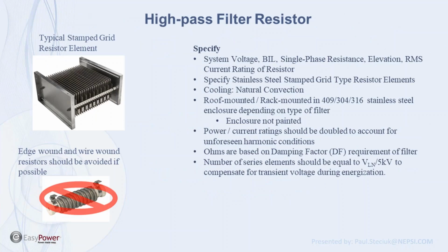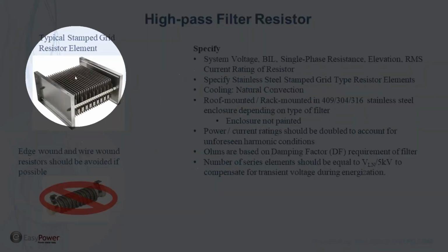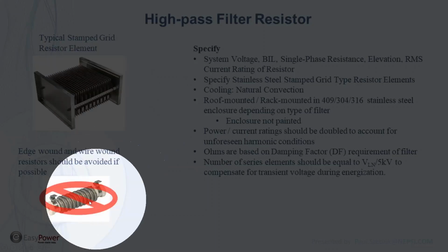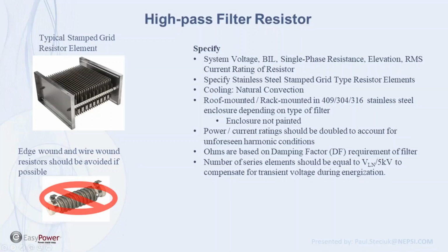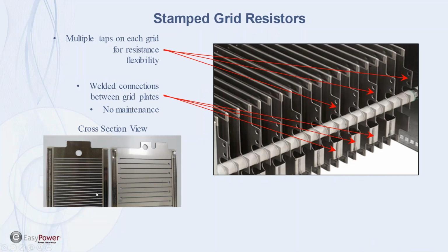The resistors are a grid type design. And here again, I recommend that you always go to a reputable supplier. In the United States, there's Avertron and Post Glover, the only two that we would recommend that we know of. We recommend a grid type resistor, stainless steel grid, and not this winding type of resistor because it can carry inductance. Here's a close-up of how that resistor looks.